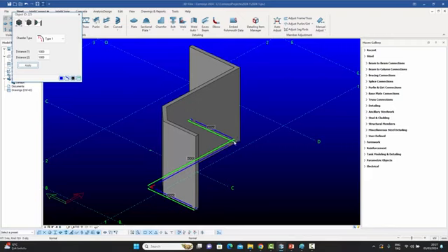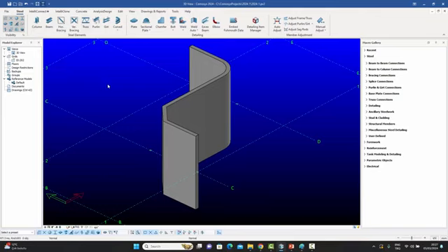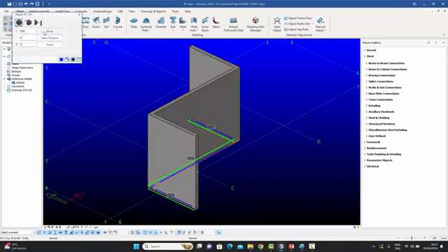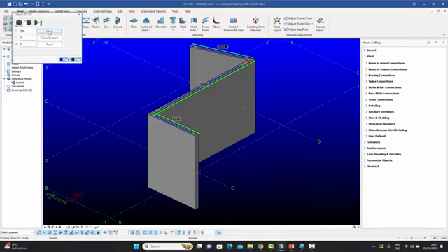Similarly, you can go and select the other chamfer, enter that, give it another chamfer variable, for example, and it's much easier like this on the screen. Let's just undo that. And similarly, you can also select those chamfer points and just move them directly. Like I said, you can move them in the X direction, the Y direction or the Z direction. Or if you wanted to, you could select a surface on the screen and those points, just like I showed you for the frame element as well. This is a very useful feature where you can extend that point to another surface, which you can select on the screen.